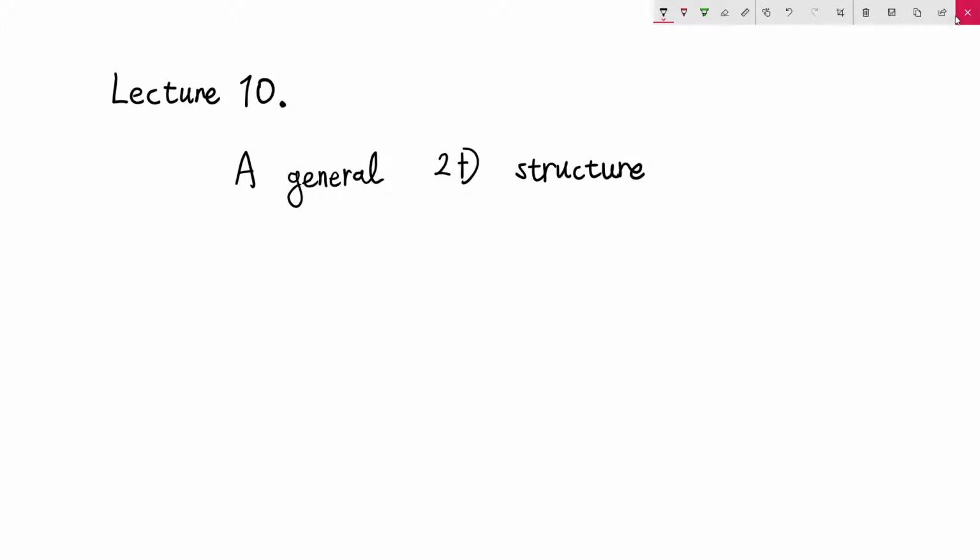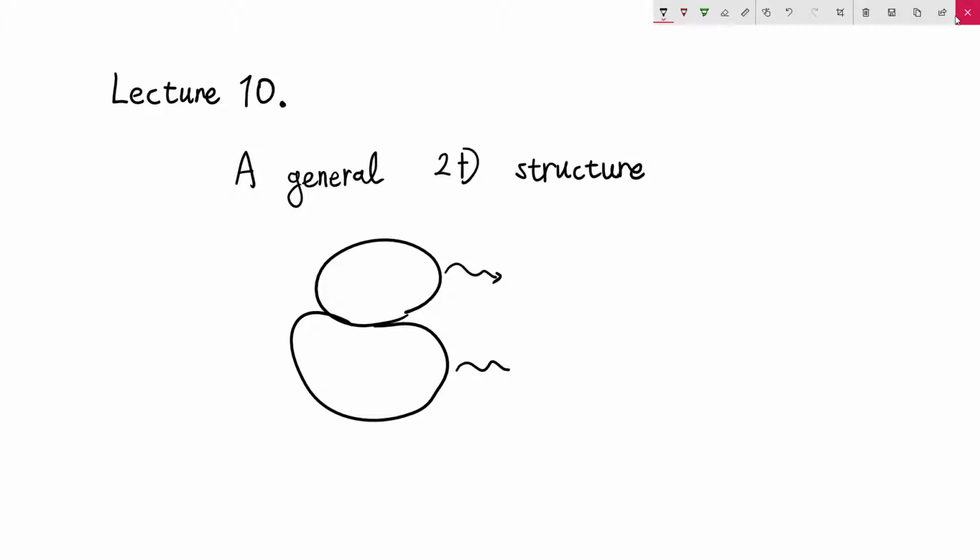So the main point was, if we have multiple regions, then we have to consider unknown variables corresponding to each region. For certain points where two regions meet together, which we call interface nodes, we can have two different variables at the same physical position but with different material properties.